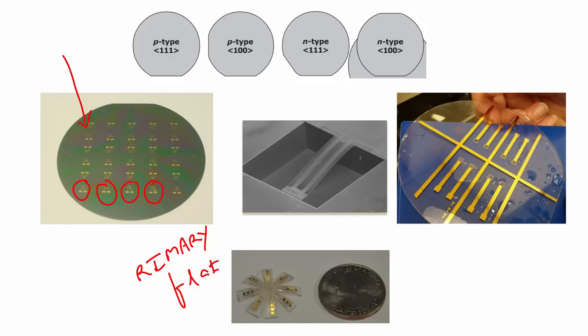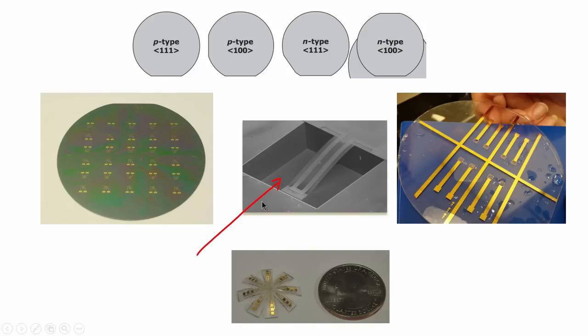That is why, when you see the screen, what I will show you in the following lectures is how you can fabricate a simple device, which is nothing but interdigitated electrodes, IDEs. This is an oxidized silicon substrate, and we will see IDEs. Then if I just clear the screen, so that it becomes easy for me to write. If you see this particular figure, this is a piezoresistive micro cantilever. You can see this is the piezoresistor, very clearly, excellent.